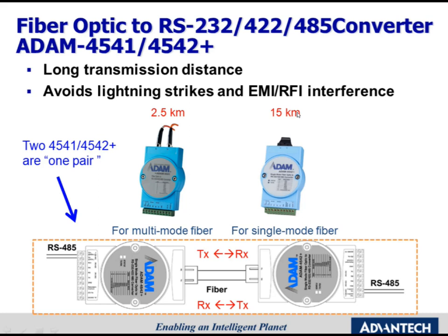The wiring method is to connect TX to the RX of the other module, so the user needs to use two converters at the same time to extend the RS485 network. It is not suggested to connect one fiber converter module to another fiber port of the customer's device, since there might be a mismatch problem due to the different device.